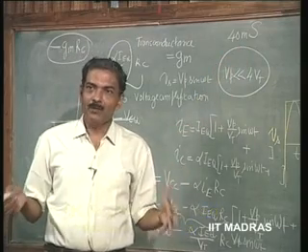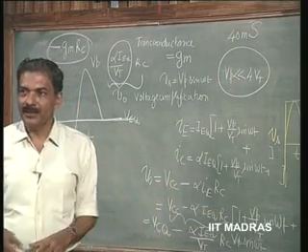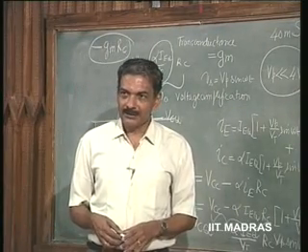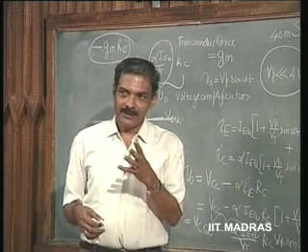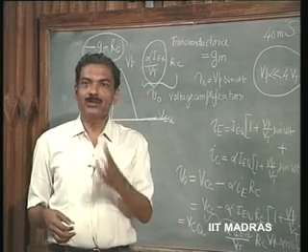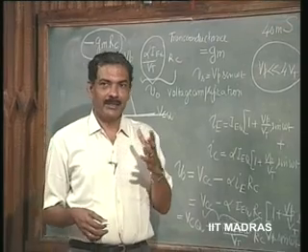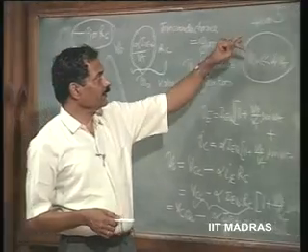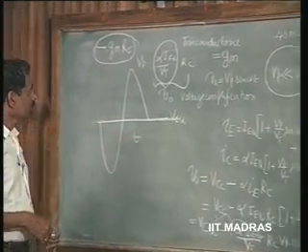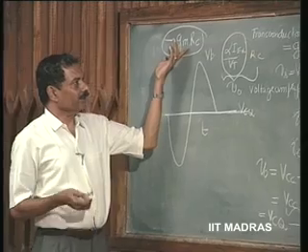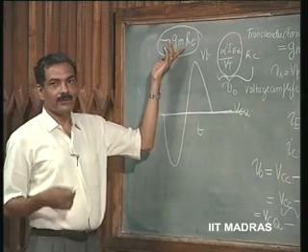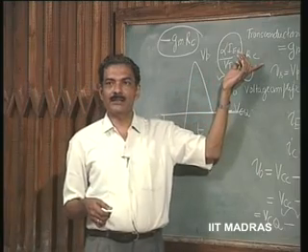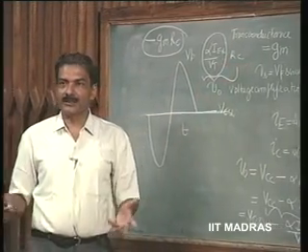So, if you just know what the operating current is, you know the transconductance of your bipolar junction transistor. That is not the case with other active devices. The greatest advantage of the bipolar junction transistor is you know most of its story the moment you know the operating point. So, this is an important factor that you should remember, that the transconductance is immediately known the moment we know the operating current. And if you fix the collector resistance Rc, then the amplification factor is also known.